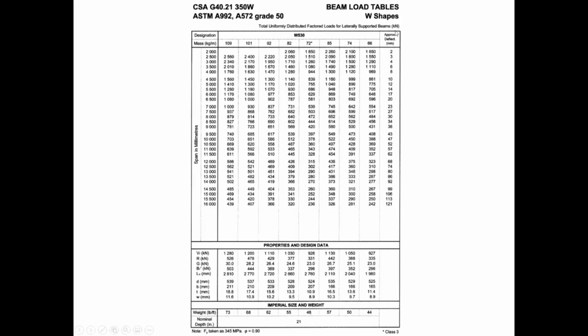So for example, if I look at a drawing, here's a column, and what the structural engineer does is this: here I have a W530 by, let's say, 76. And he gives you that the span from here to here is 4 meters. So what did he design the connection for? Some people will tell you what the shear force is here for the beam, and some don't. Some drawings are done better than others, but if you don't see the shear force there, then you can reasonably assume that this beam is going to have a maximum uniformly distributed load acting across it.